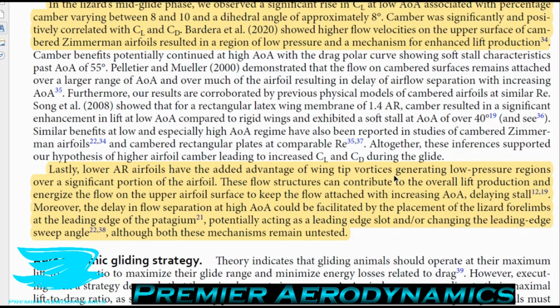So how does the leading edge sweep angle help? It changes the stability characteristics, but also in this case, it won't change the lift characteristics too much, because the airfoil section is already very thin. It could help with potentially increasing the strength of the wingtip vortex. But again, that needs to be tested with this case. I doubt it. But anyway, that's the end of this podcast.